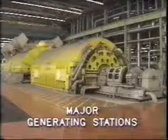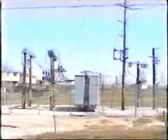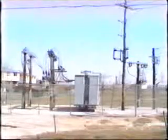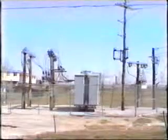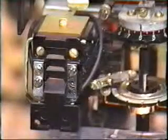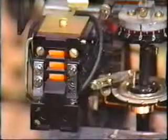Also, every major generating station, and every station with interconnections to other systems. Normally, oscillographs are not located at the distribution substations except those installed to analyze special problems or to conduct research. But it is just as important to analyze incidents occurring on the distribution system as on the high-voltage power system, even though you may not have the help of sophisticated recording equipment. In this area, you will have to rely upon operating reports, including relay target data.